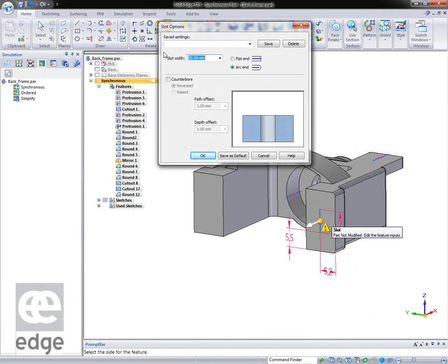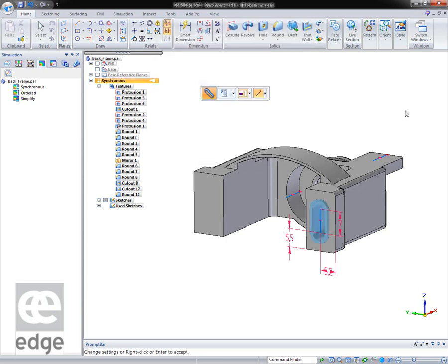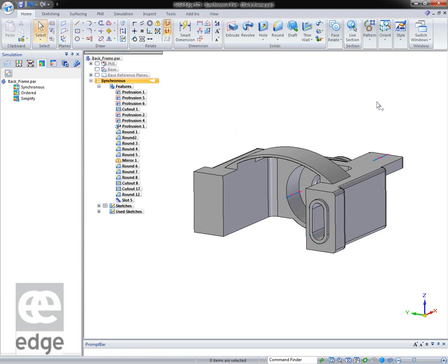I want to make this one 4mm, and I want to do a counterbore, but I don't want to have a recess. I want to raise this, so it's 1mm and 1mm. Say OK to that and push it through. Again, the same command bar comes up, the slot extents, or the normal thing I want through next, and there we go. Right click to accept that.